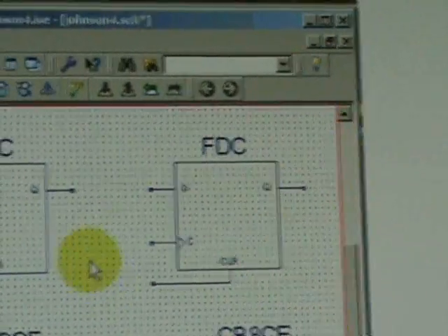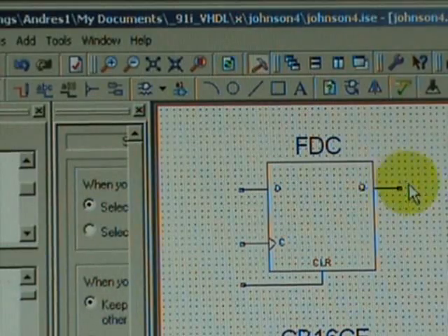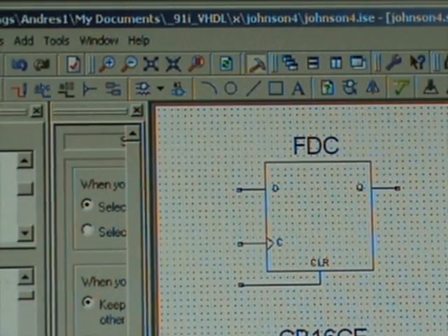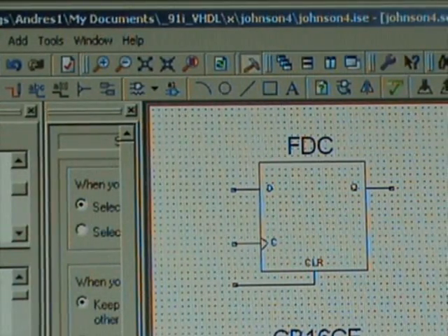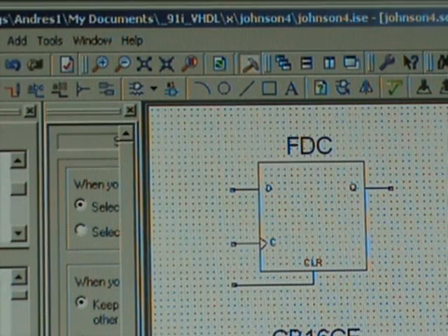So we will position this so that this one is the D output, this is the C, because the B is feeding the A. And then the output of A is routed back to here, and we connect here an inverter.